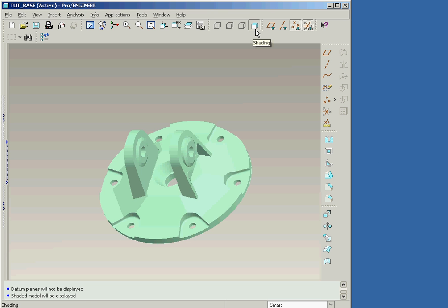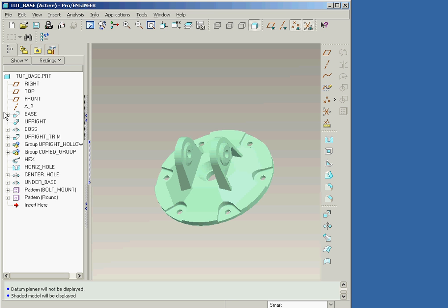As we will find in the subsequent lessons, the creation of parts in Pro-E is accomplished by constructing a series of features. The list of features used to create a part is displayed in the model tree, which we'll open now, by opening the Navigator pane and making sure that the Model Tree tab is selected. As you can see, as we click on a feature in the graphics window, the feature's name is highlighted in the Model Tree window. We can also click on a feature's name in the model tree and see the corresponding geometry highlight in the graphics window.